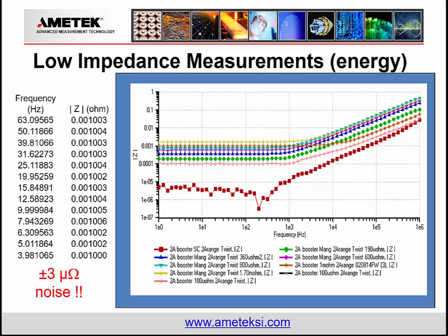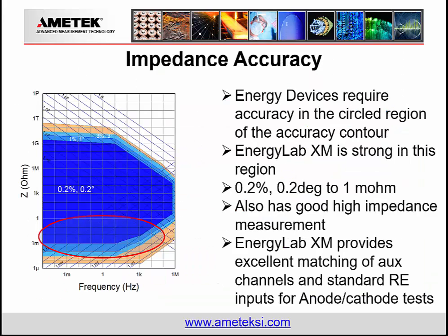And if I continue to run those at different calibrated resistor levels, we can build up what's called an accuracy contour plot that defines the impedance accuracy here. So the highest accuracy region is 0.2%, and you can define both the impedance range and the frequency range over which you have different levels of accuracy.